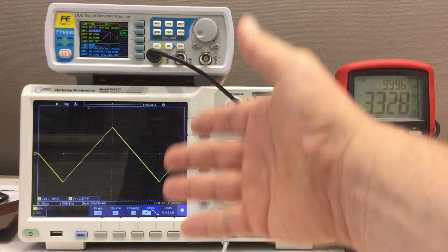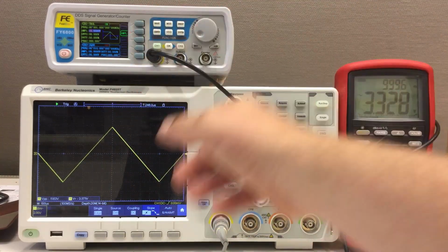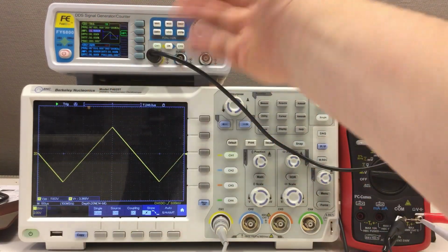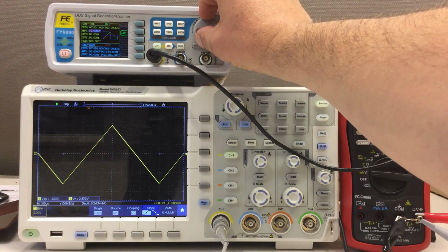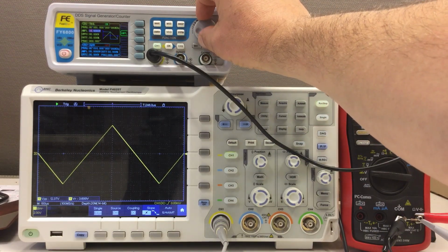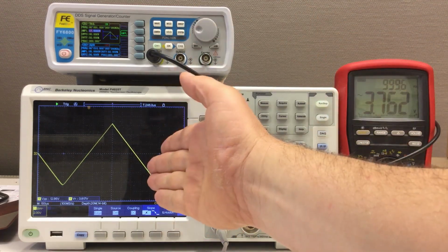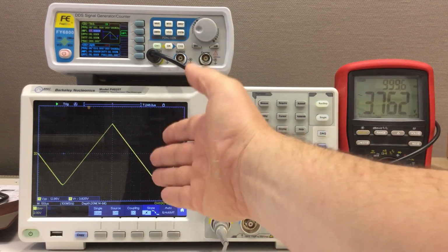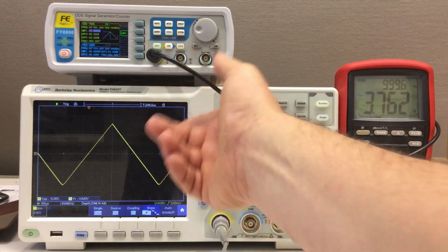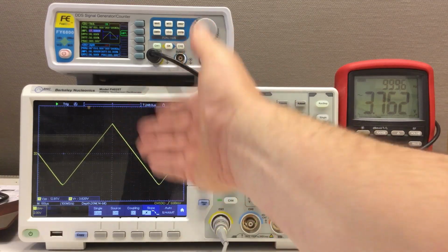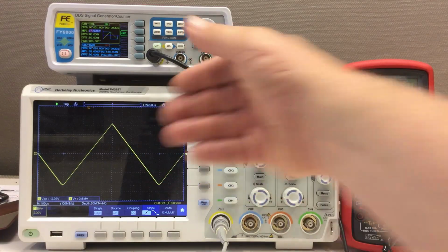Okay, this is really getting ridiculous. I'm, again, at triangle 15 volts currently, and 16 volts is okay, but 17 volts is a distorted signal. We are at the end of the ladder with a 158, it measures in at 158 ohms load resistor.